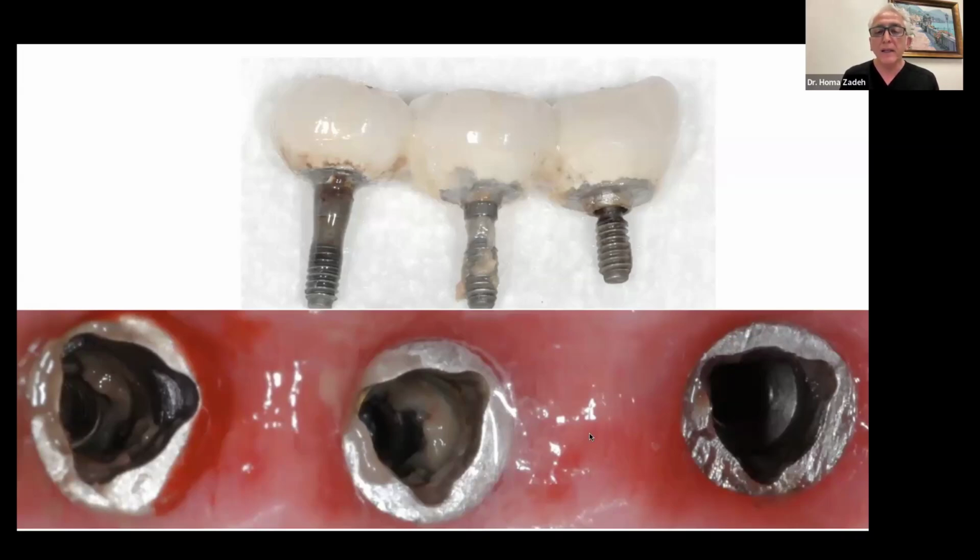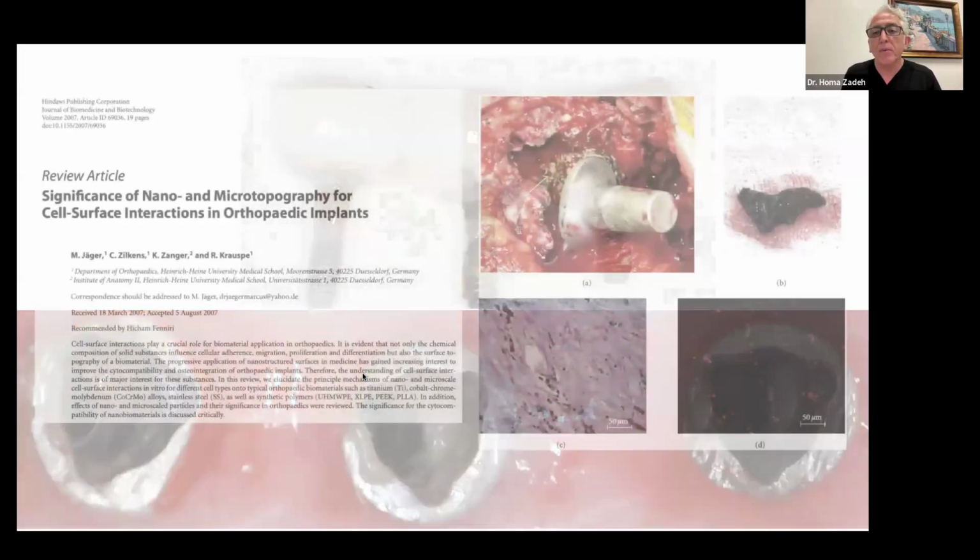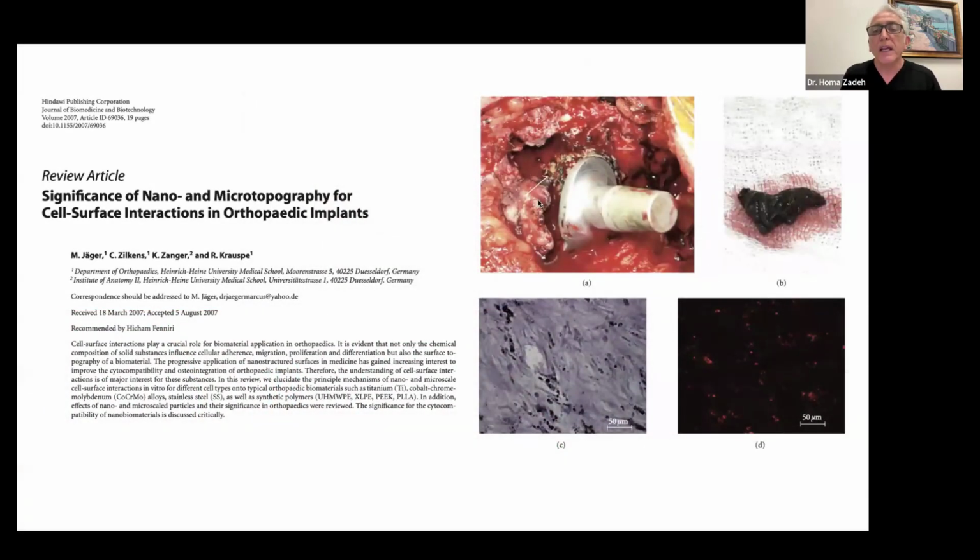But one other thing that we became aware of is that this kind of metal on metal is very similar to what's happening around prosthetic hips. In prosthetic hips, it's been known that there's a phenomenon called metallosis, where small titanium particles released into the tissue are encapsulated and phagocytized by phagocytes in the tissue, causing lots of inflammation and leading to failure of many of these prosthetic joints.